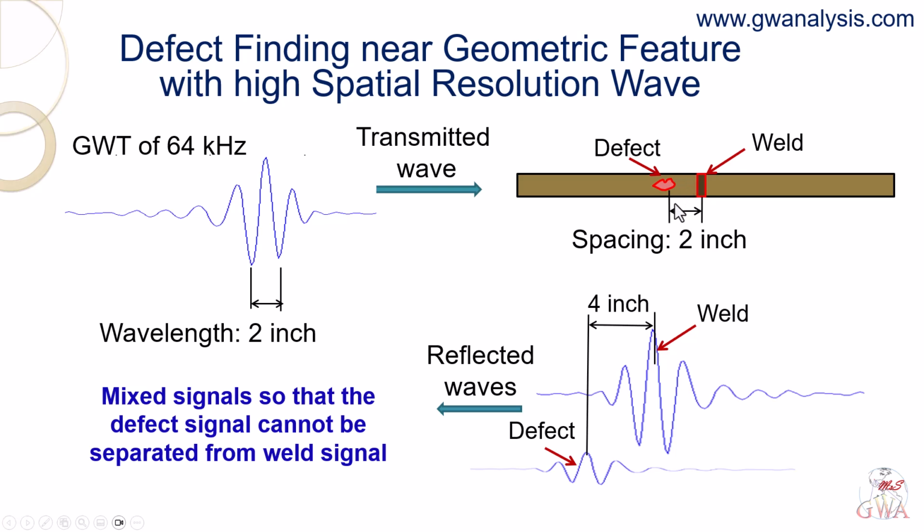Because of the round-trip travel distance, the reflected wave from the weld and the defect appear 4 inches apart in the recorded data. Using the one-cycle 64 kHz signal, whose signal width is 4 inches by probe design, and checking the video signal, the rectified envelope signal, rather than raw RF signal, the two indications are just resolved as separate. This is a borderline case, not a wide margin.